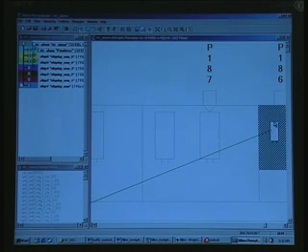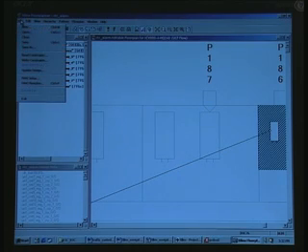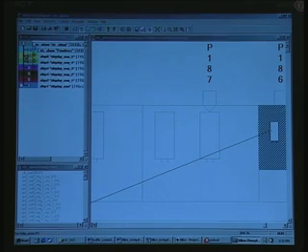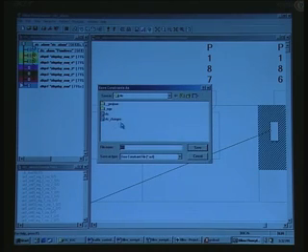If I am not happy, I can change my mind a number of times, relocate anywhere, and then what you do is under file you have one what is called, sorry, write constraints file. If you click on this constraints file, you can save the very constraint file, these are all relocated pins, and once again you have to run the implement. After that the new changes that you have made, either in the form of relocating the components and or the pin, will be shown here, and this is what is floor plan. This will be done only at the fag end of your project.